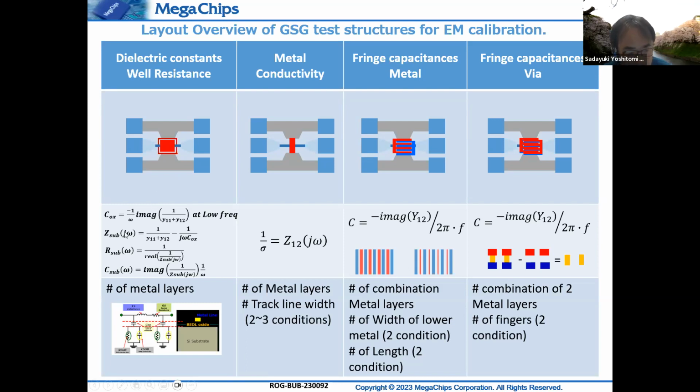And here you see the four equations in this table. These equations transform to each parasitic parameter extraction, such as COX, the coupling capacitance to the substrate. This is represented in this figure also. And substrate impedance, G sub, is a parallel combination of R sub and C sub.